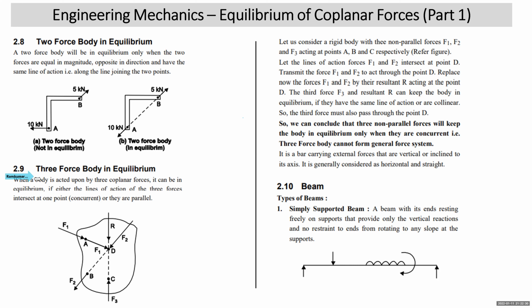Do remember that a three force body cannot be in equilibrium under a general force system, right? We have to remember that if they are parallel, three parallel forces can keep the body in equilibrium. If they are not parallel, they have to be concurrent. So this conclusion helps us in solving many problems, right? I will justify this statement.